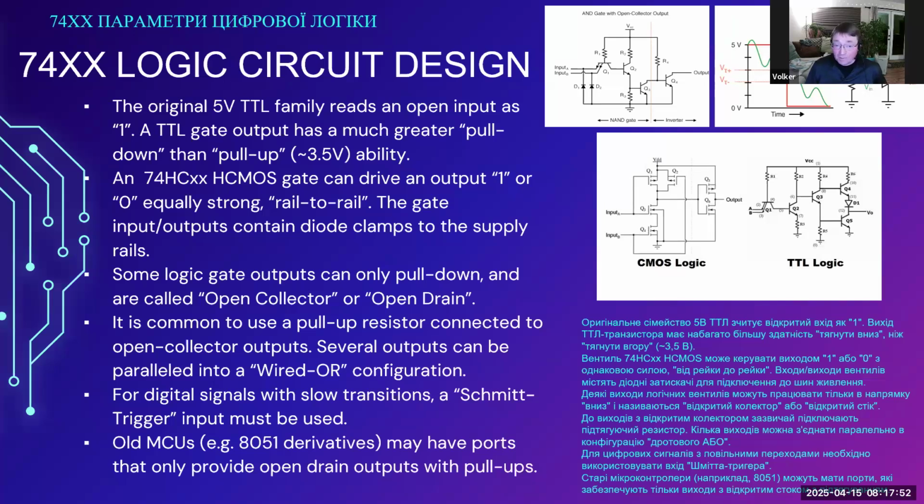For today's CMOS gates, the difference is that the gate input is high impedance and cannot be left floating. In the old TTL technology, a gate input could have been left floating and it would be detected as a high. The newer technology logic gates cannot be left floating, because in that case, it would just simply generate oscillations. It would pick up noise from surrounding EMI. So those gates require a dedicated pull-up or pull-down resistor.